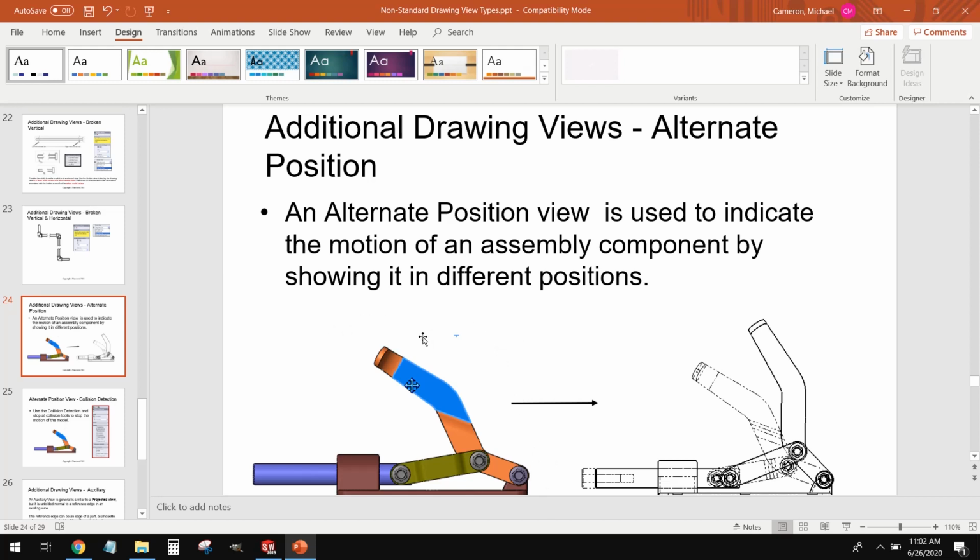But when they go ahead and try to move this in the real world, when they try to build this, they'll notice that because they built it to the closed scale, and they didn't have any reference for it when it was open, they can't actually use this clamp in there, right? It'll hit the lid of the enclosure. That's a common issue in engineering, right? A lot of times we're designing fixtures and enclosures and pieces with parts that we don't actually have on hand. So knowing the full scale of the dimensions when this part is in its extremes is important to us.